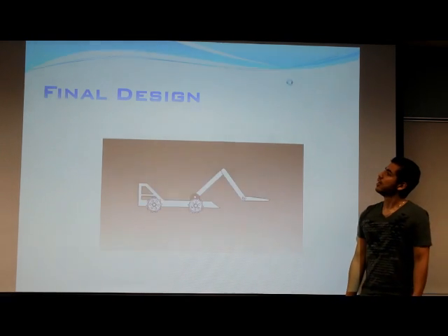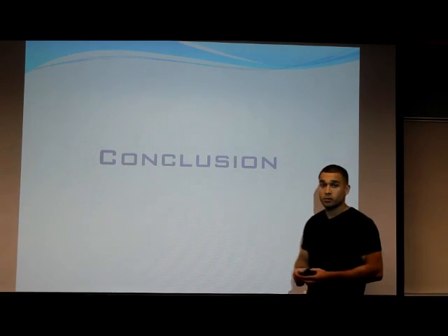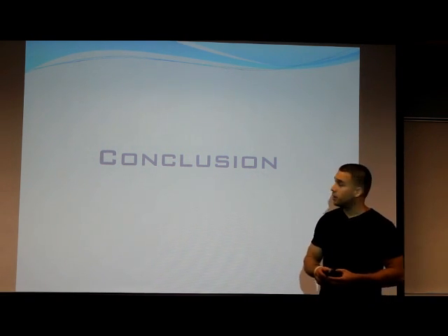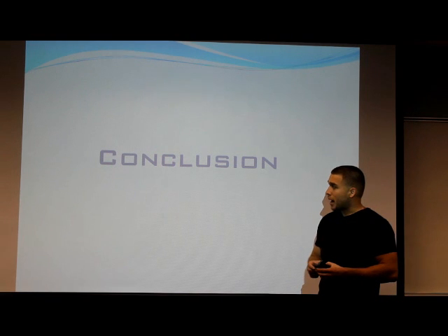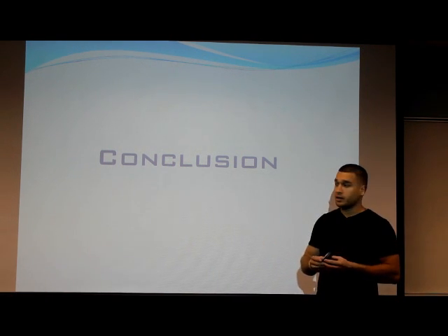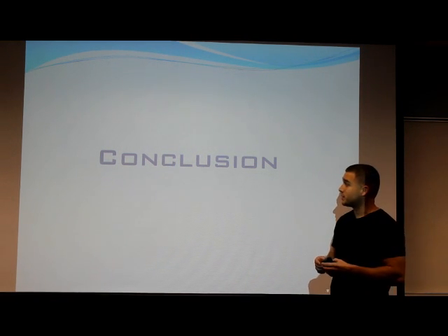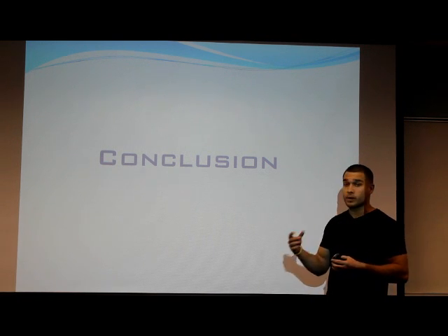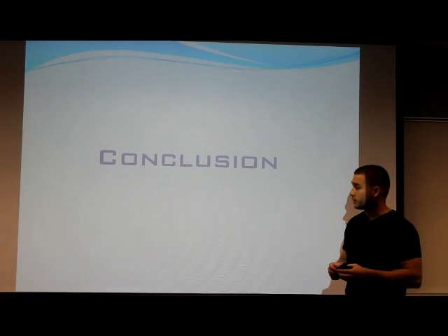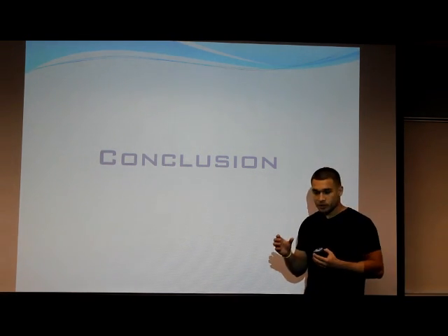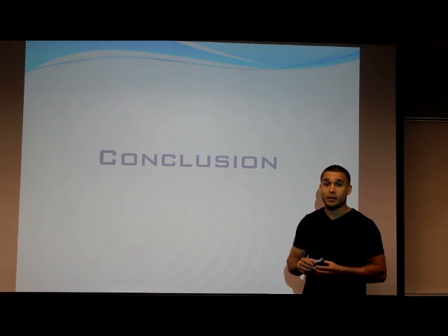And now we have the conclusion. In conclusion, we kinematically analyzed a 3-revolute robot. Initially, we did a path analysis which was parabolic, which yielded imaginary results. We quickly fixed this issue by simply changing the path to an elliptical one, which yielded more feasible, more practical results. Also, in the dumping process, we chose a vertical path to be the most optimal path.